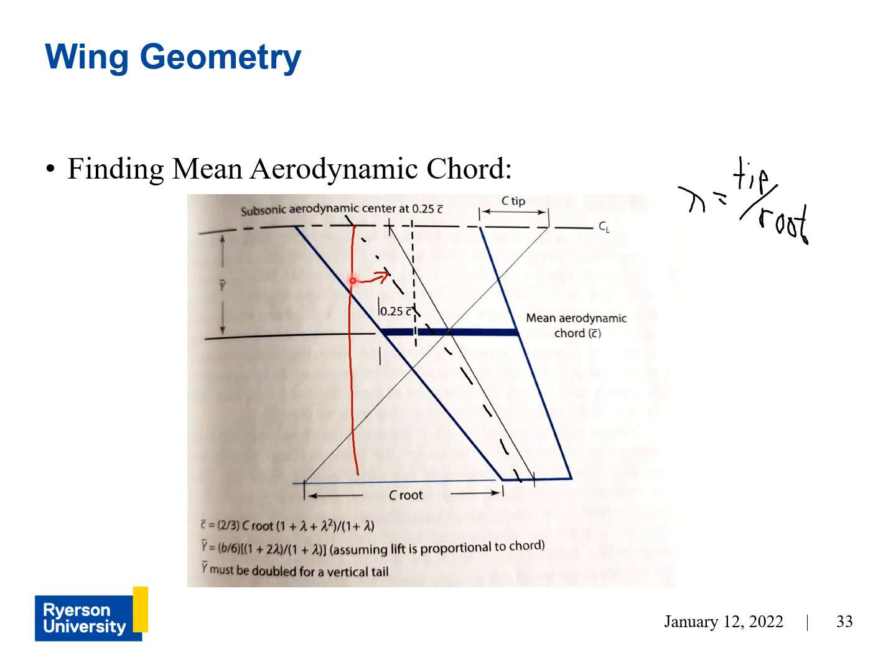And that parameter is more relevant, I guess, for subsonic flights like gliders, as opposed to the sweep angle for the leading edge, which is more relevant to supersonic flight. So if you want to put a sweep on your wing, you'd want to pay attention to this line as opposed to your leading edge.